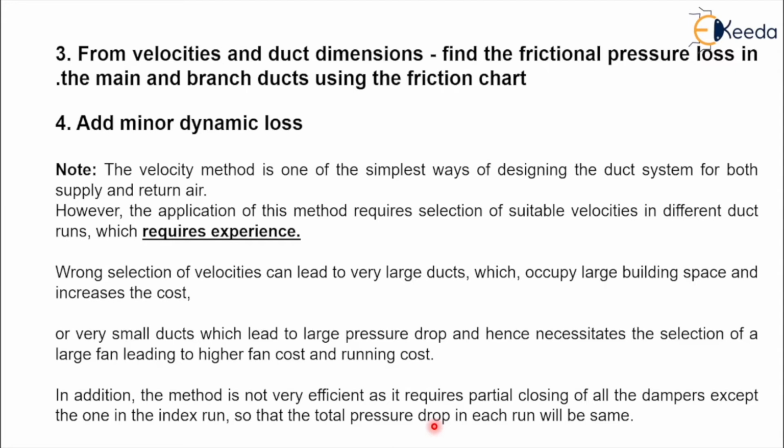Why? Because how do you maintain the total pressure in each run the same? With the help of dampers. Every time you have to partially close the damper. By partially closing the damper, you will reduce the pressure. Because of that, there will be major losses. Because of that, losses will increase. If losses increase, then it is not a very efficient method.